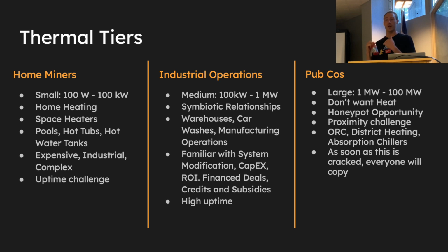But right now we have those temperatures that don't exactly overlap for these systems to work with Bitcoin miner waste heat. You know, one way you could add a little bit of waste heat to get the temperatures where you want them is off-grid, right? You have combustion then from natural gas. So you could take some of that heat off of a combustion process. That'll be most of your heat, honestly. And then just add a little bit more from your miners. Then you could drive that organic Rankine cycle.